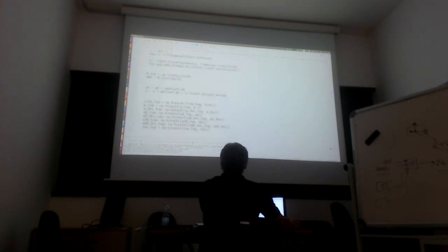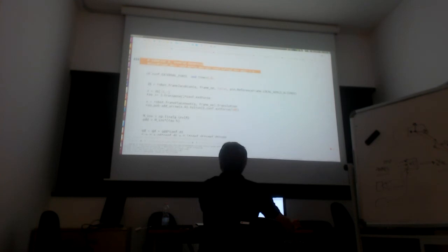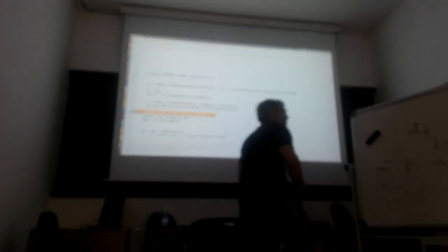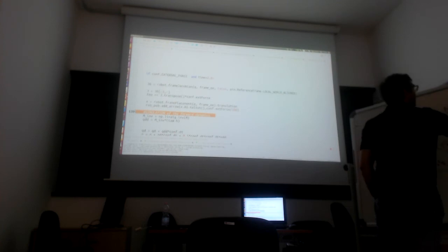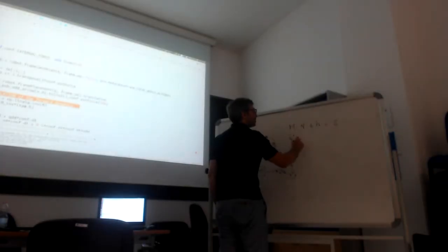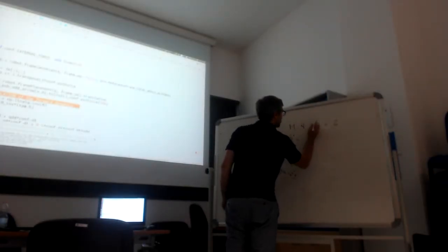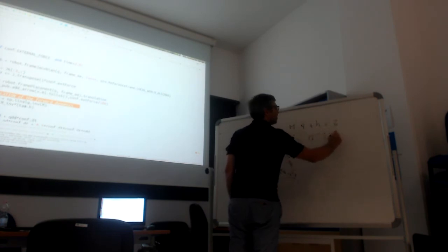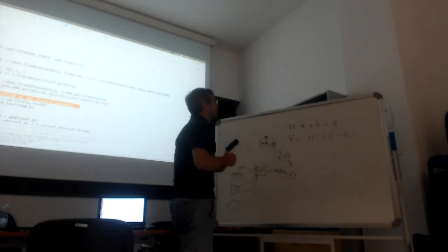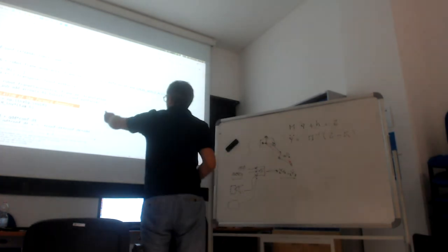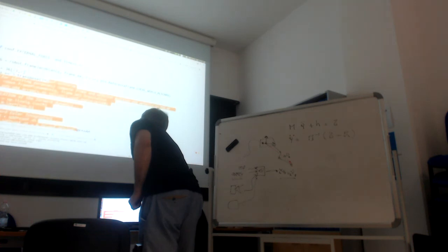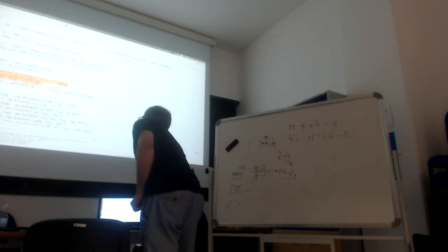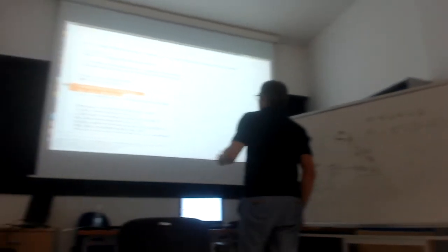And then finally there is the computation of the dynamics, simulation of the forward dynamics, which is in essence inverting the dynamic equation, because we have M q double dot plus h equals tau. So we compute q double dot like M inverse times tau minus h, and then you integrate with Euler integration to get the velocity and then the position.